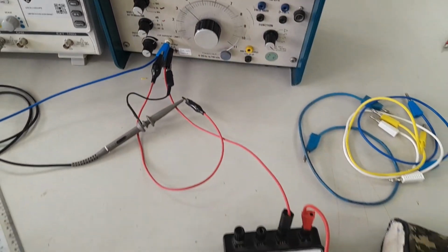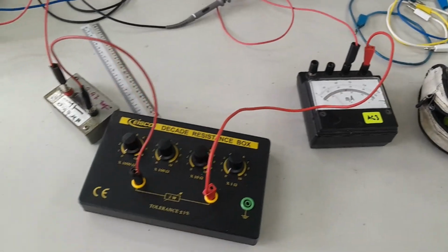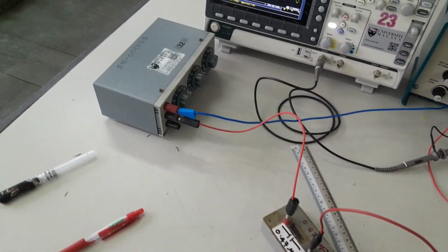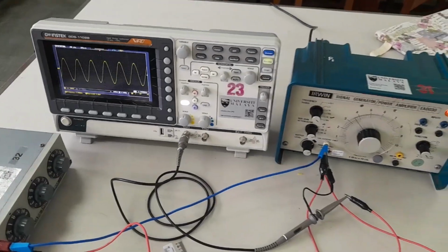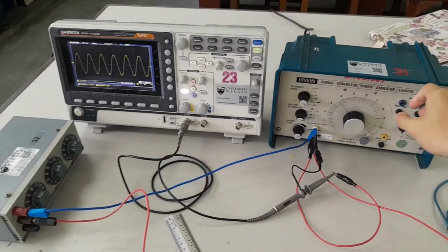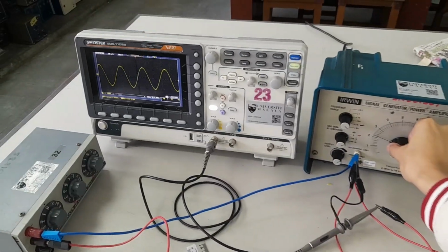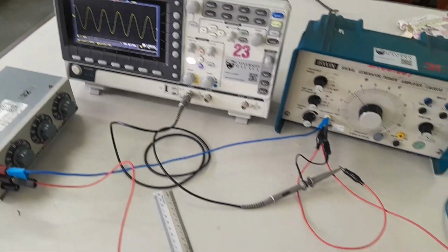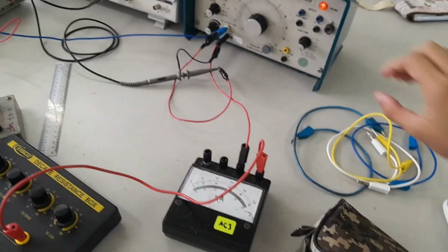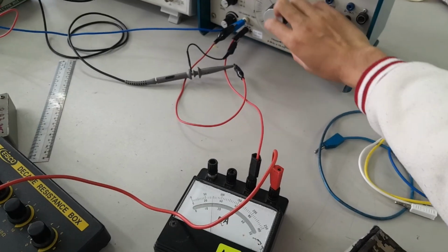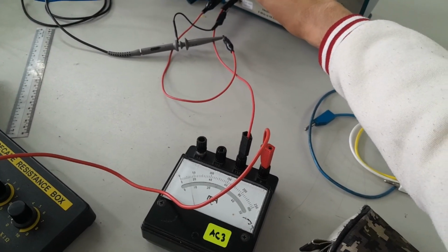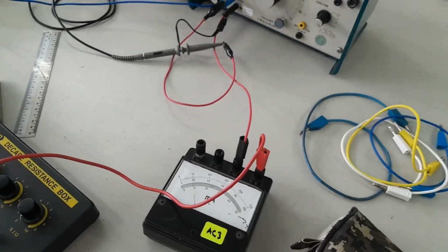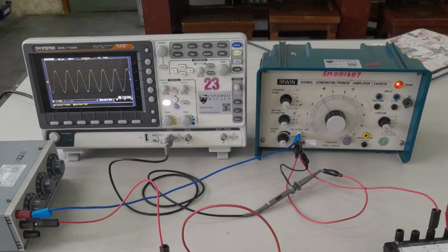Firstly, I arranged the circuit as shown in this figure. I set the resistance at the signal generator of impedance at 10 ohms, and later determined the currents at different frequencies. These steps are then repeated using 20 and 50 ohms. From what I observed, the current from the ammeter is at maximum at a certain frequency. That is actually the resonance frequency. Also, I noticed the difference between the frequency in the signal generator and the frequency displayed in the oscilloscope.